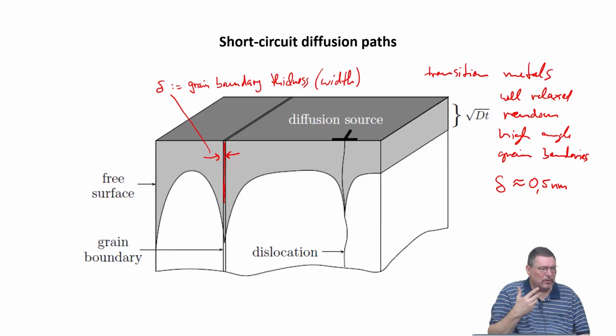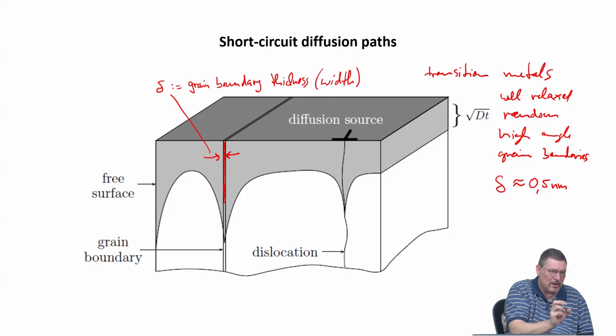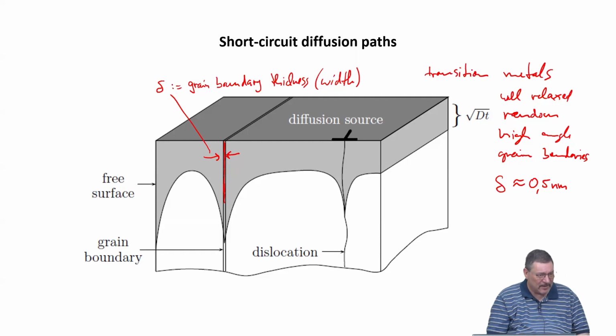These values could vary a little, so it would give you something like, again, between 0.5 and maybe up to 2 nanometers. And that depends very much on the thermodynamics of the system, like how large is the segregation tendency, for example, of a material. So this is why it's a little bit more complex. We can, for all these alloys, have proper measurements and proper definitions, but not all the definitions give the same mathematical value for the width.